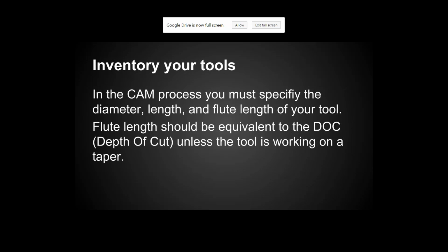Next slide. Okay, now, let's say you're slotting a 1/4-inch hole, you're typically going to be running a tool that is smaller than that profile. There is a slot command in Fusion's CAM processor, but typically that will cause a bit of a conundrum if you're going exactly the size of your tool to your slot. You'll cut chips up, the chips will re-weld themselves to the sides of the slot. Typically, you want to have a smaller tool than the profile you're machining.